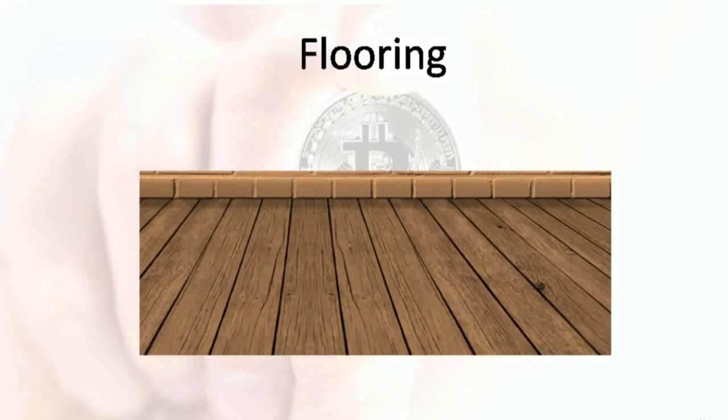With flooring, especially if you have a greenfield facility design, you can choose between raised floors and hard floors. Let us look at these two options. Let us start with the raised floors. The main use for these is for airflow circulation, such as the targeted and enclosed architecture that I will be going over in the later cooling section. Now, aside from cooling, you may consider raised floors for the purpose of routing cables or establishing a ground grid for your equipment.